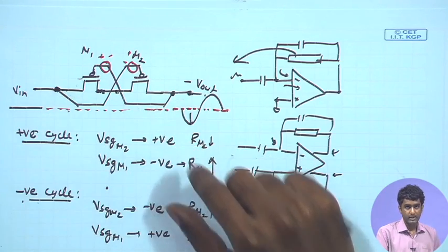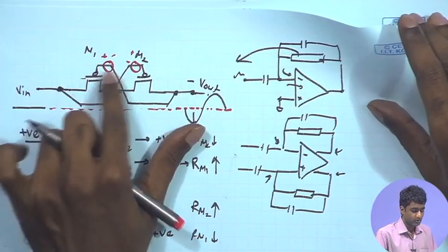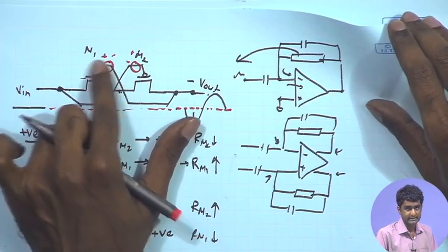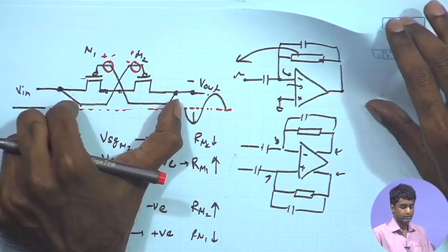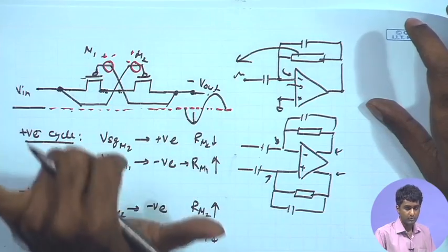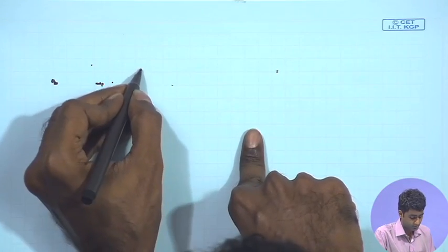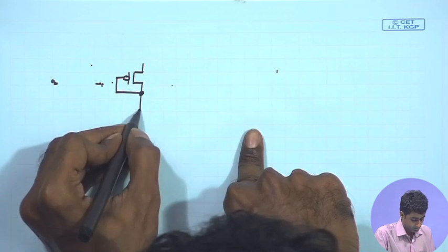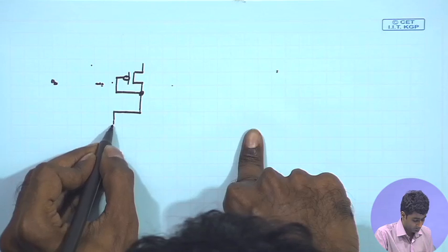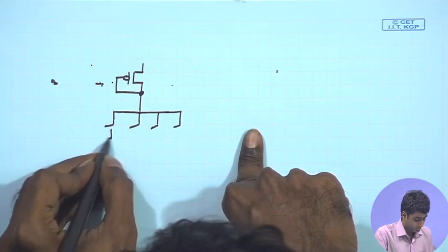That is one way through which we can control the overall resistance provided by this device. So, let us just look at one possibility, how can we create such a battery and put it in series with this MOSFET, so that the overall resistance can be reduced, and we can try to simulate that example also and try to see how we can obtain such a control in the device. So, one possible way of implementing such a transistor level battery is to use a tunable current load.